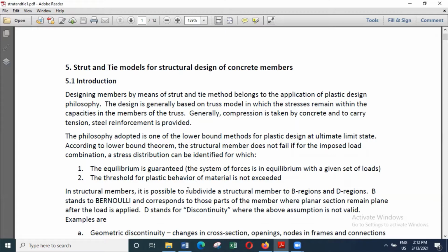So that's why we like materials like steel, concrete, which can demonstrate certain amount of ductile behavior before the failure occurs. And then we make sure the stresses in the material also remains sufficiently low. And in the case of steel designs, generally we make sure that under normal service conditions, the stresses will remain even sometimes less than the yield stress.